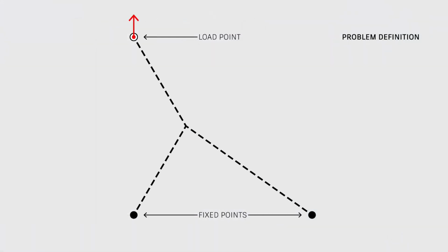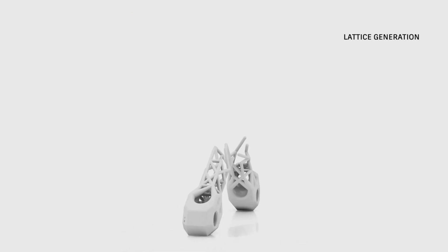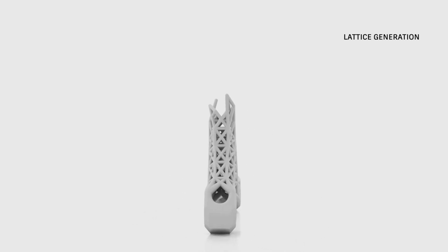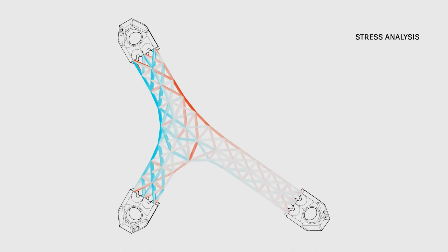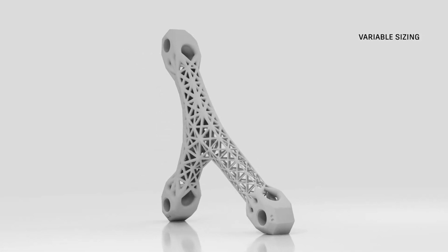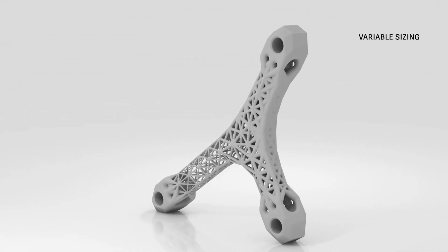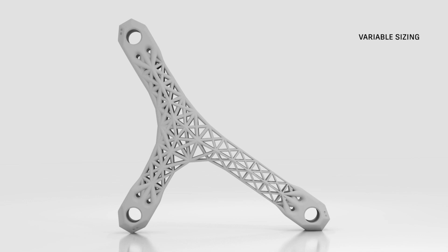At any time, you can adjust your specified goals, and generative design will reanalyze the data and deliver a fresh set of solutions based on the updated design criteria. You're also able to tweak your design further in Fusion 360, and you can even export the selected solutions to other design and analysis tools. One key point is that these designs have been created with manufacturability in mind.